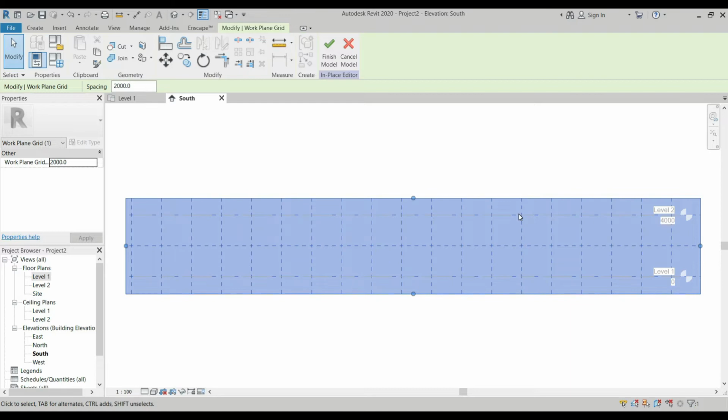So when is the time that you're going to use the reference plane, and when is the time that you're going to use the reference line? Usually in families, you're going to use a reference line if, for example, you want to create moldings. The reference line will help you to create those moldings since it is a linear production, or you have to create it in linear.